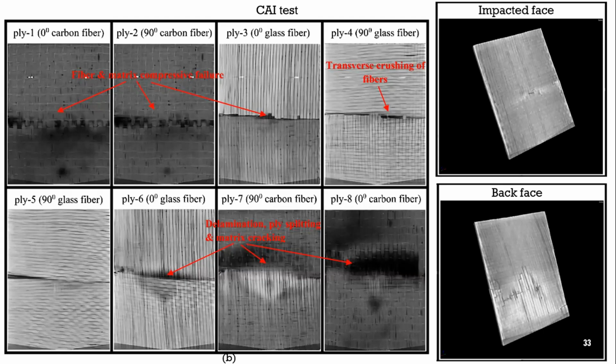So instead of removing them from the laminate while doing hand layup, you can remove all these air pockets during your matrix phase itself, before mixing the hardener with it. So you just go for some vacuum assisted air bubble removal. Those types of things you can think of for this one, but in general everybody faces that problem. So here also, I will show you.